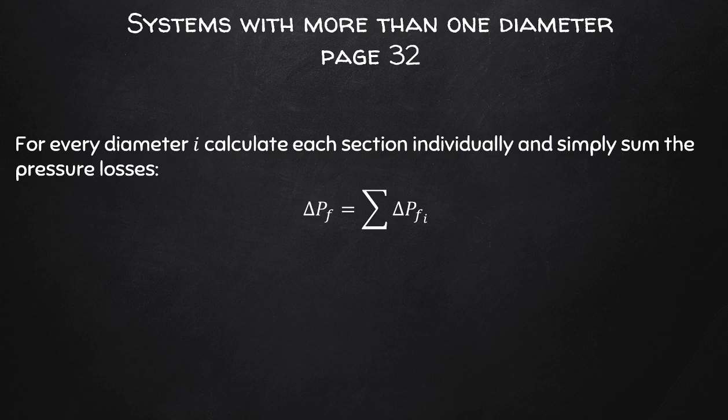If we have some pipelines where the diameters change, we typically talk about reducers or enlargers, or maybe you have just two different pipelines entering and leaving a process. We can still calculate the pressure drop across this or these sets of pipelines by adding additional terminal points or splitting up our calculations and then summing up all the calculations in the mechanical energy balance.